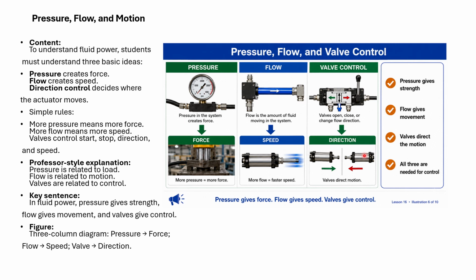Pressure is related to load. Flow is related to motion. The valve is related to control. Key sentence: in fluid power, pressure gives the force, flow gives the movement, and the valve gives the control.